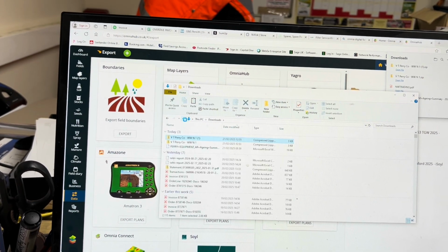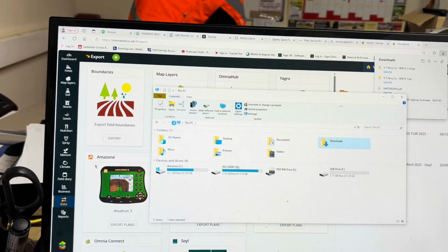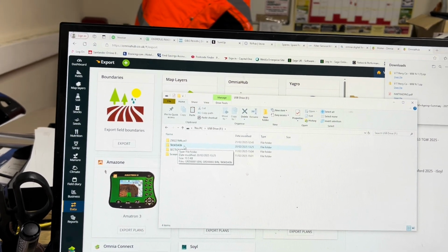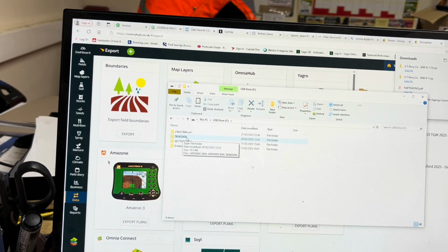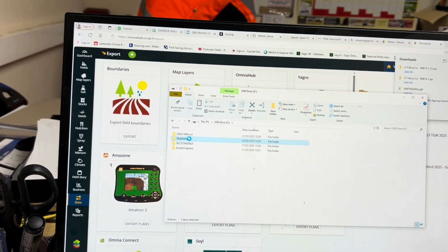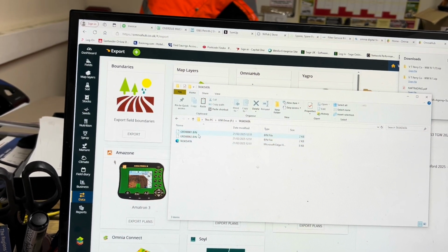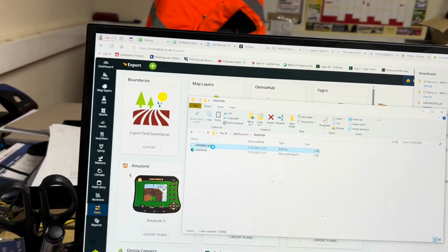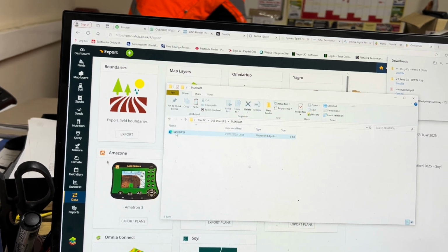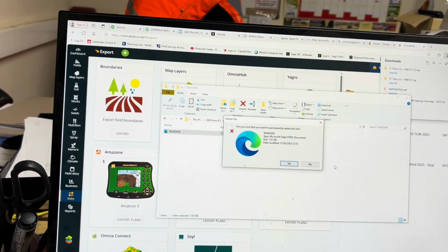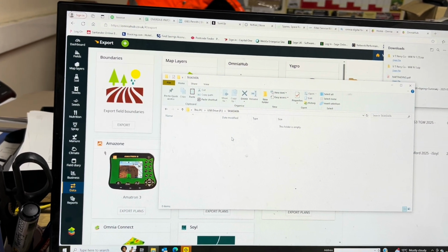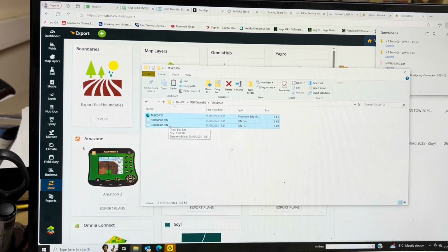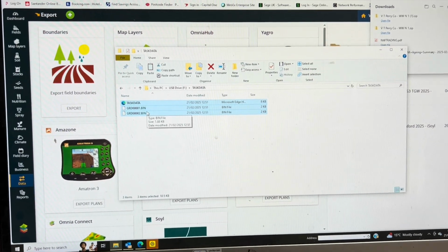USB stick. So when we go onto the computer itself, we need to go to the USB drive. You can see that in here, because it's an ISO XML file, we need to use a task data formatted folder. So double click on the task data folder and you'll see the previous files in there. I'm going to delete each individual plan. However you want to delete them, you can probably select all and delete. Once I've copied them, I can then paste in the new plans, and you can see the plans that reside there. That's all we need to do to download the plans onto the USB stick to utilize them in the